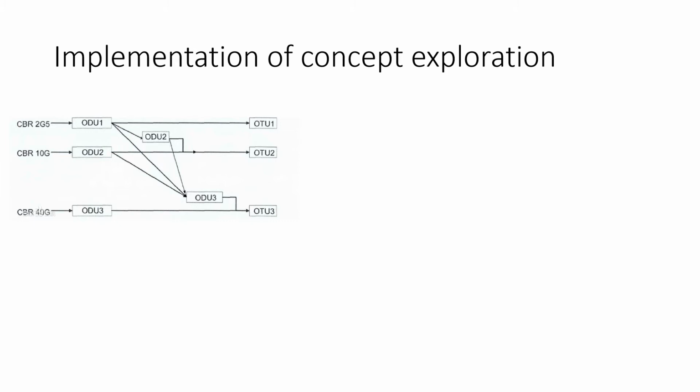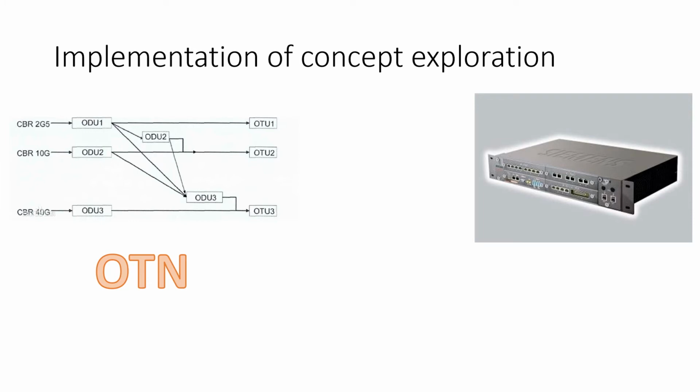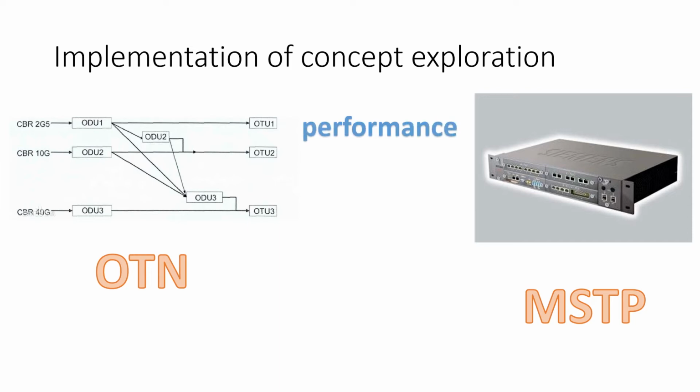Obviously, OTN is better than MSTP because it has higher bandwidth and lower delay compared with MSTP. Besides, it has high intellectualization of channel protection. But it's too expensive to apply OTN in all of the transmission equipment in the system. So MSTP is widely used in subway transmission systems currently. I believe this problem can be solved after mass production of OTN in our country.